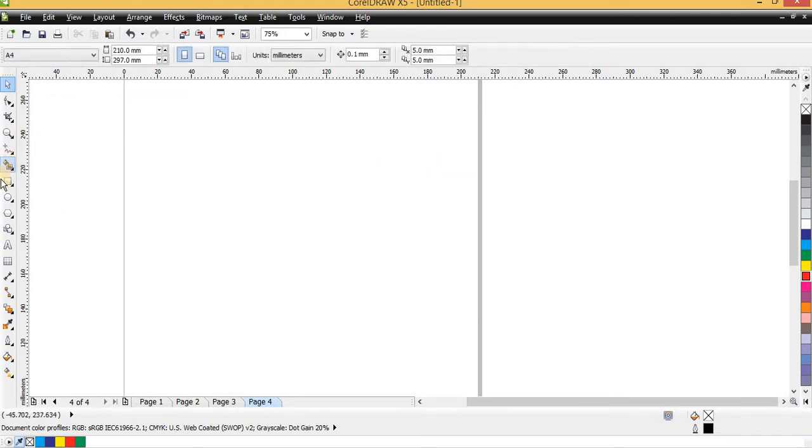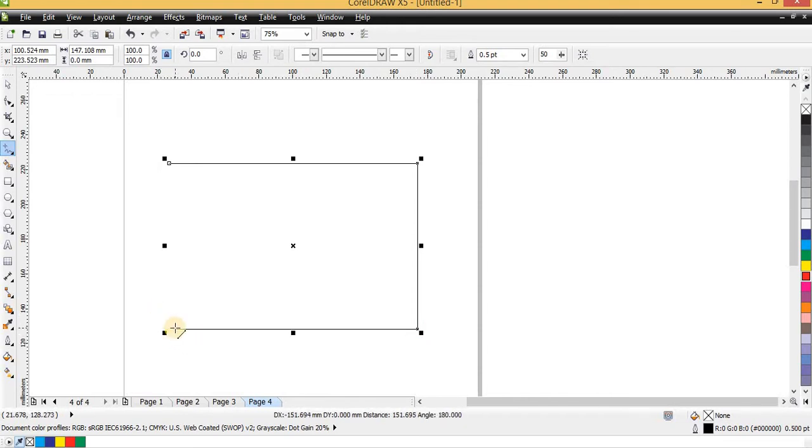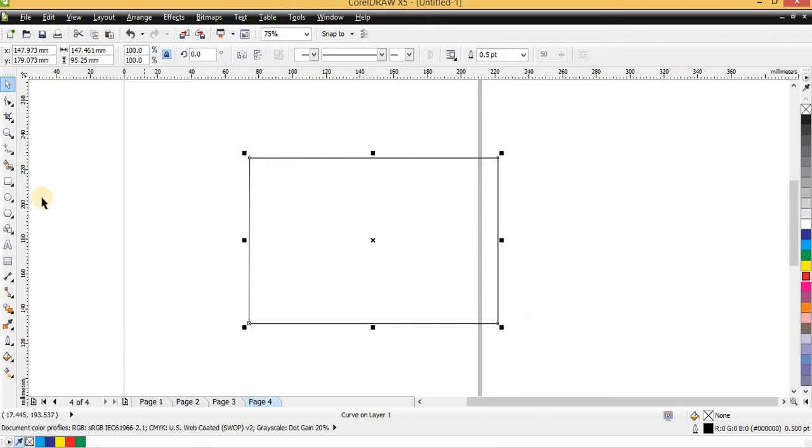I want to delete this. I pick my line tool again. So clicking from point A and holding my Shift to point B to give me a perfect straight line, I have to double click here. So having double clicked, I continue again this way. I double click, and having double clicked again, I continue to this side. I double click, and so on till I get to this point. So you can see that I can even still use my freehand tool to draw a rectangle in this case, something that might look like here.